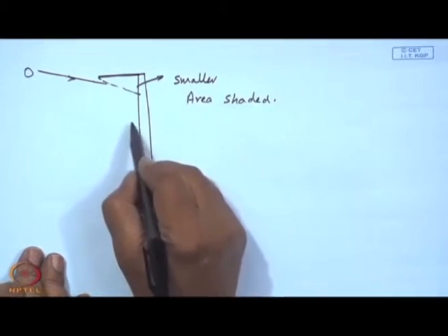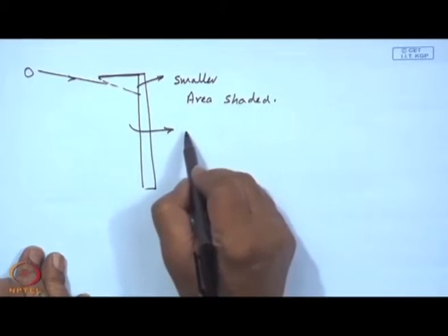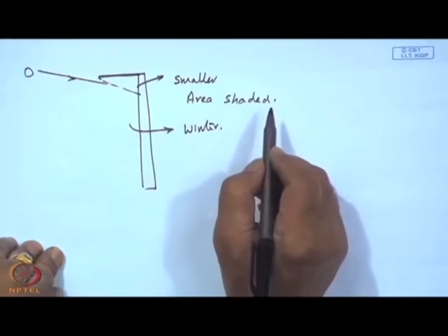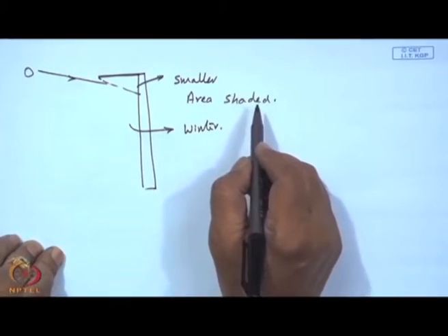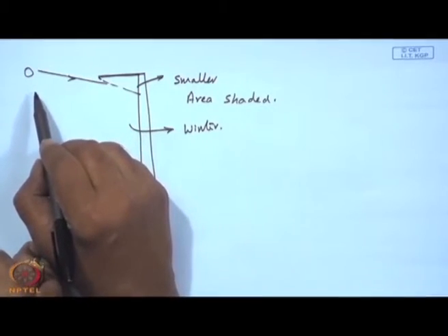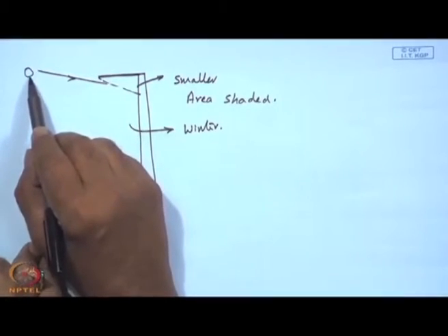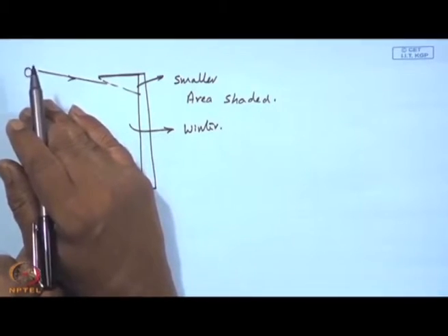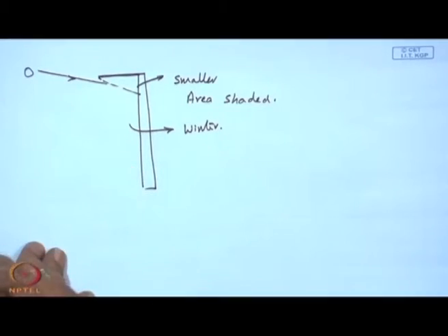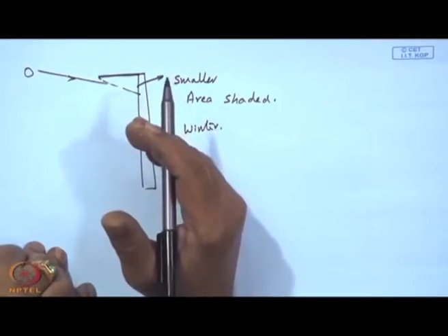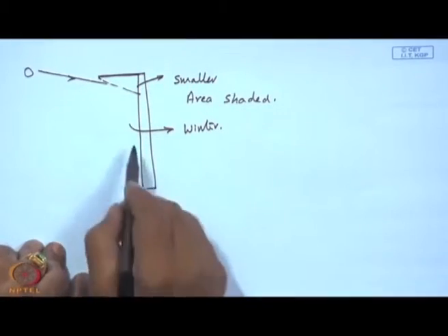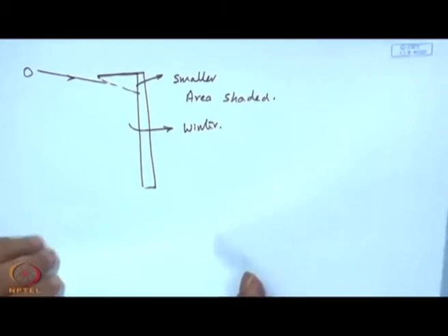So, it will let in the sun in winter, whereas it prevented so much of sun to enter during summer. The positions of the sun, at least in the northern hemisphere, as shown here, it is pretty low in winter months or declination negative in general, and in summer months it will be high up almost right at noon time, right above your head. So, consequently it casts a longer shadow shading the window.